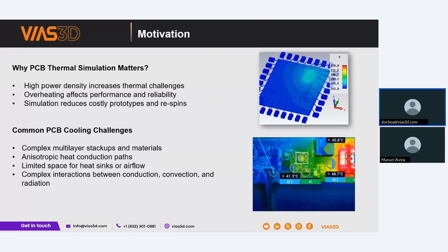There are also multiple challenges when it comes to cooling a PCB. We're dealing with a very complex multi-layer stack-up. Basically, it's an anisotropic material, especially in the Z direction, and we have limited space to cool down the device. We have to put heat sinks, airflow, or any other cooling technique, and we're working with limited space to do that.